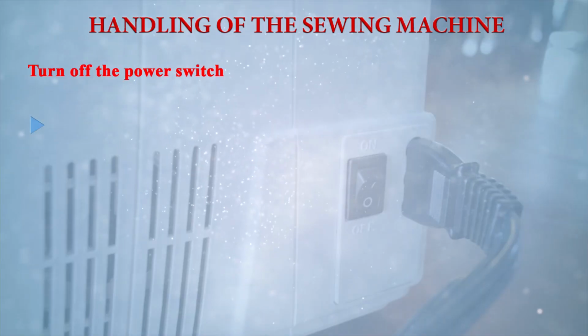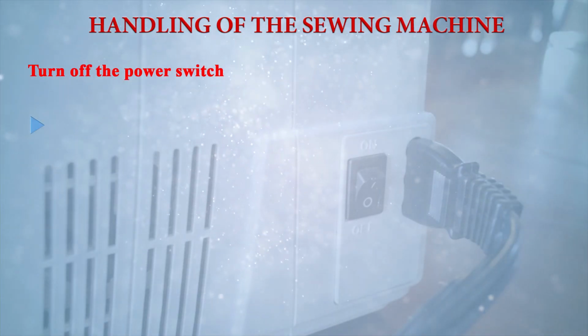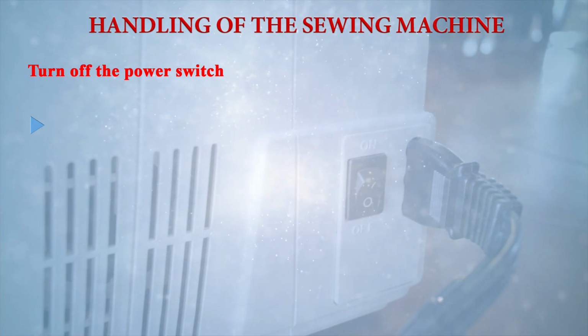So don't pull the fabric like that. Just stop the machine, then revolve the balance wheel and take the fabric out from that point. If you pull the fabric suddenly, it may break the needle and it may harm you. So you have to turn off the power switch.